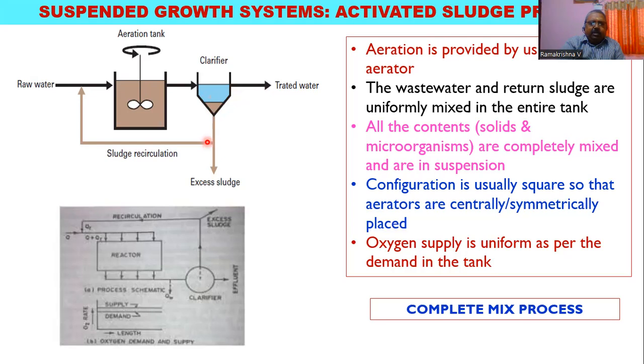In other words, if we talk about an aeration tank for about 4 hours and another 2 hours in the sedimentation tank, in total only 6 hours of life we are utilizing when making one complete cycle. But the active life of this biodegradable material, or the active life of the microorganisms, is more than these 6 to 7 hours that we are keeping.